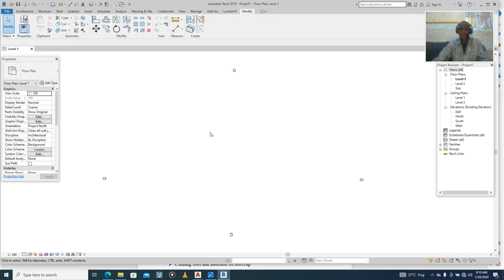Then you can also copy by using our function keys. Ctrl C simply means copy. Everywhere, Ctrl C. In our normal MS Word, Office programs, it is still the function key. Assuming I highlighted something, I want to copy it, you can use the function key. Hold the control button and press C. We'll come to use it when we start modeling. You can decide to highlight a wall and copy the wall and drop it somewhere else. You can use the function key, Ctrl C.